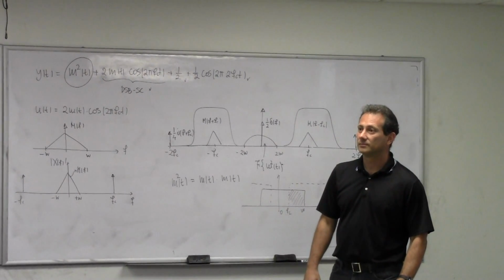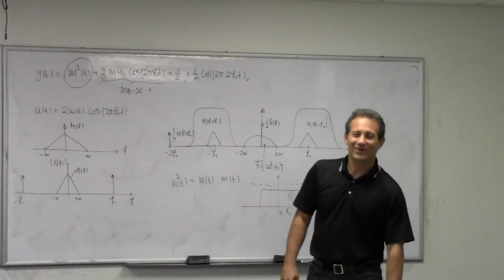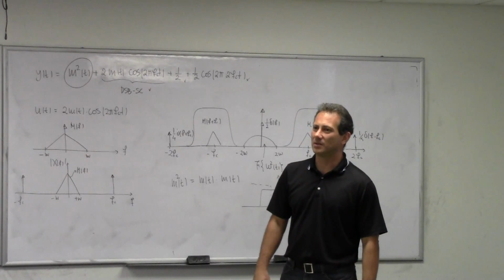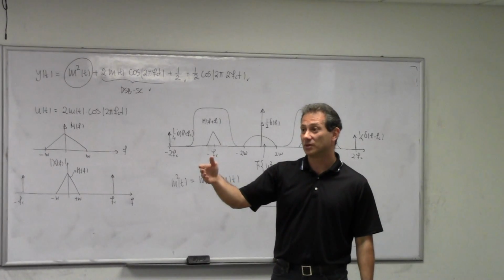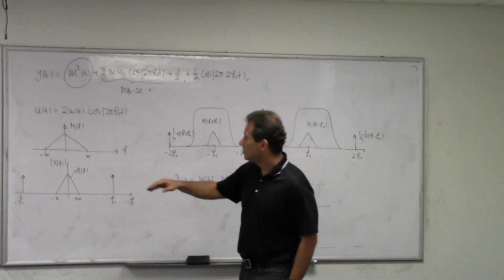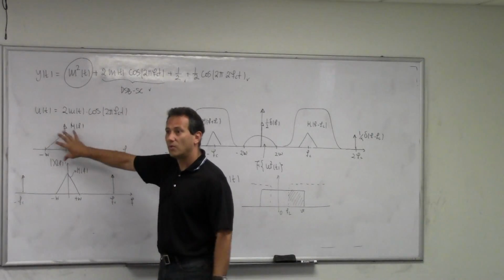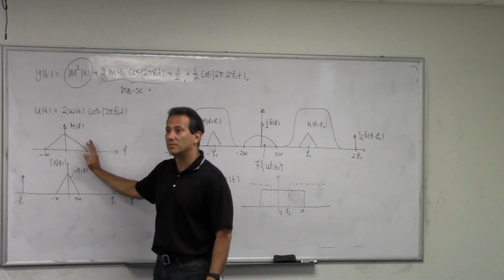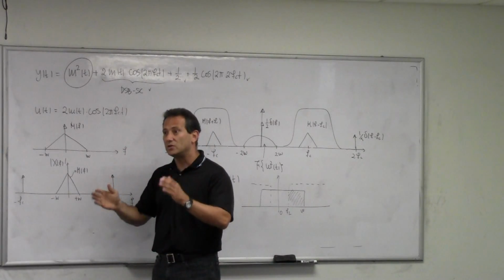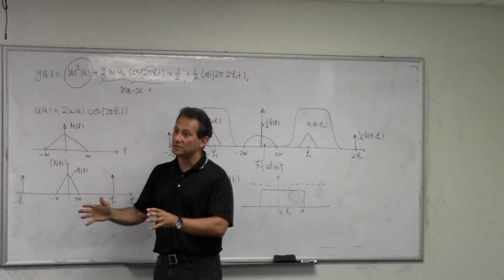Which one do you favor personally, the most out of these three filters? No, low pass, because most of the problems that you're looking at are demodulation problems. When you demodulate, this is what you need, and you get it out of everything by low pass, because your signal is from 0 to W, and you're going to have all of these other components that you're trying to get rid of. So the specific use of the low pass is in demodulation as the last filtering stage.